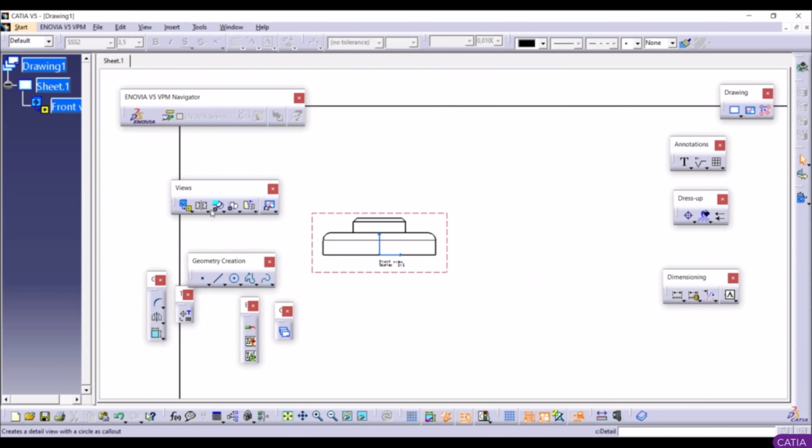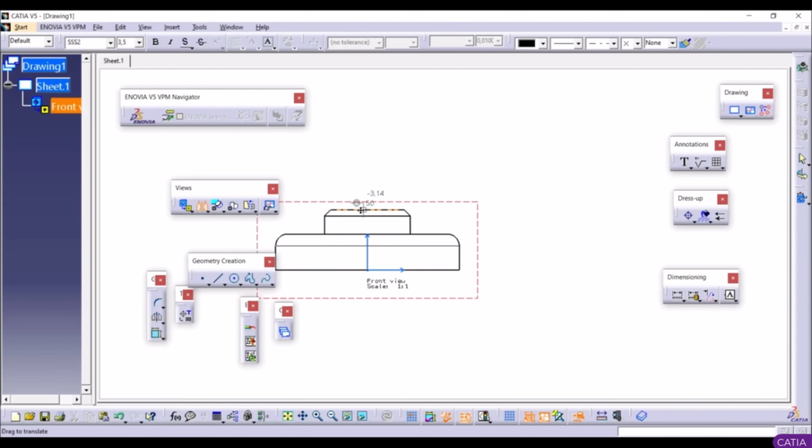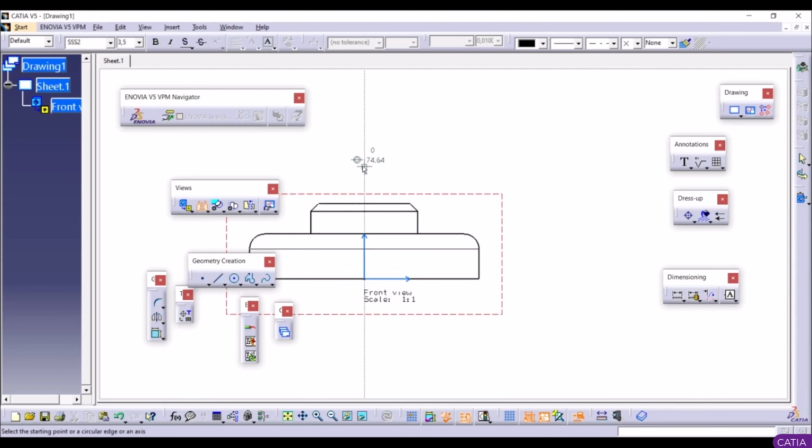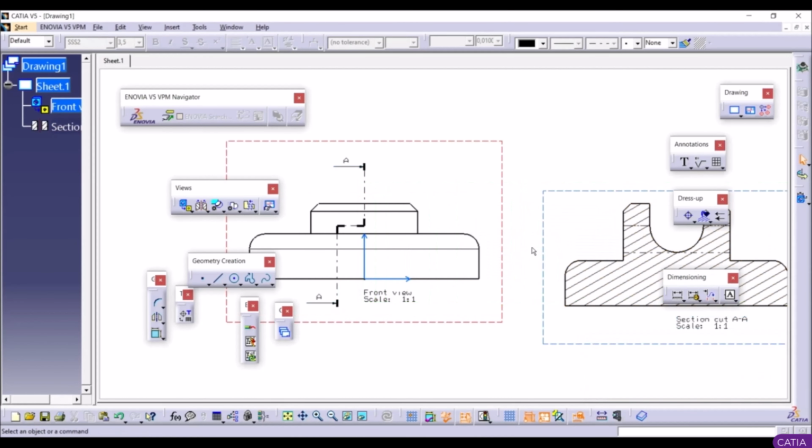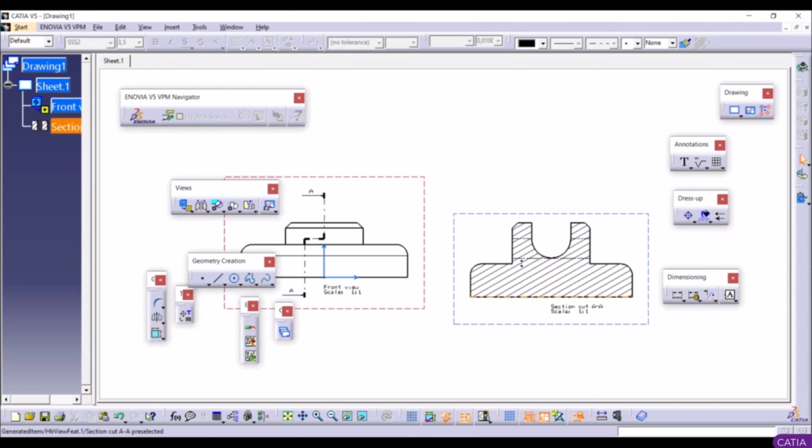Now the last tool that we have here is this one here, and this is aligned section cut. The same thing, but we don't have to go with a straight line. So we can go here, let's go down, let's go to the left, let's go down, like this, and let's double click to end. Let's go to the right side, let's position here. And this is the surface that is left out after sectioning. So this is how we can use section tools. Let's delete this view, right click and delete.